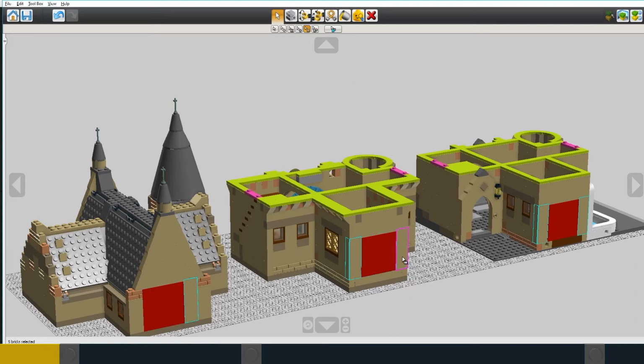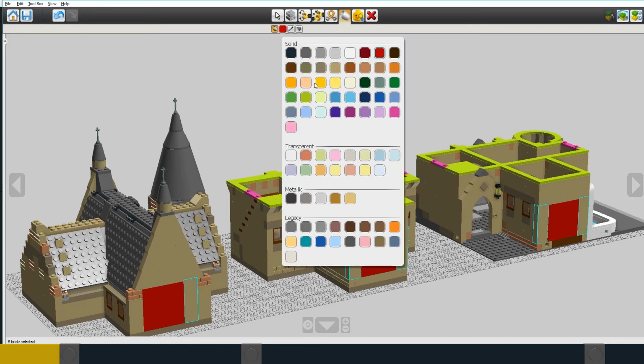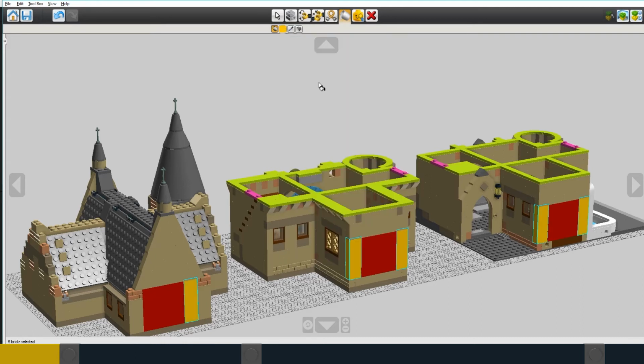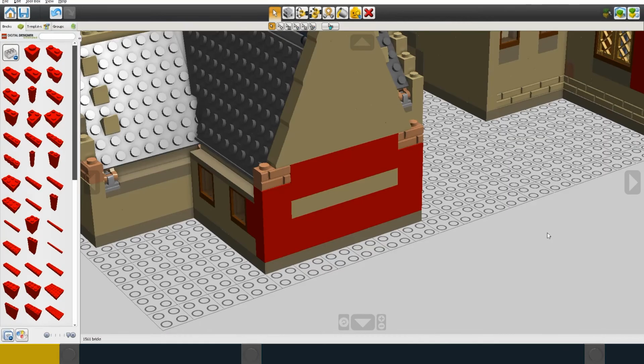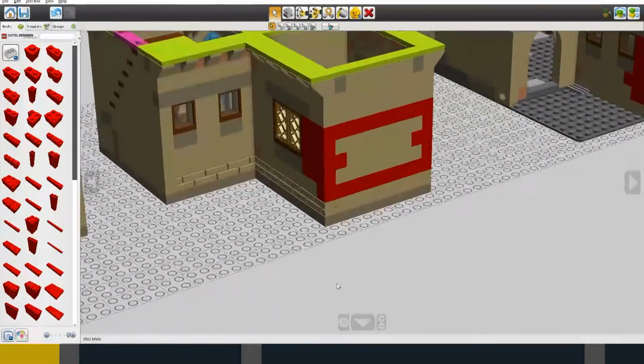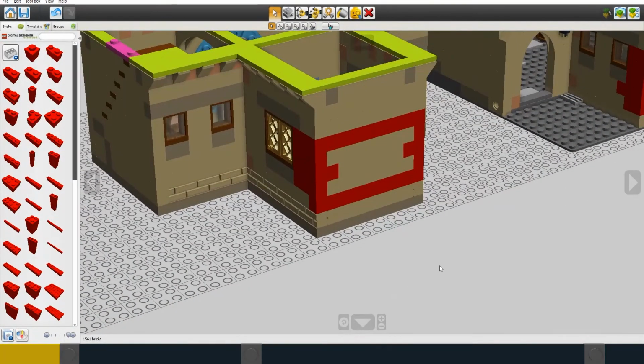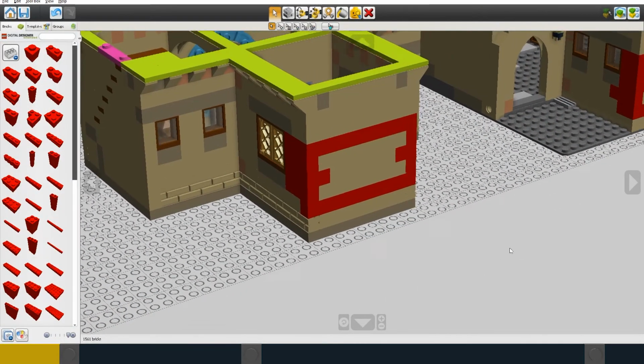But as I've gone round the exterior of the building, I've replaced many of these panels with other bricks so that I can provide details like door surrounds, window locations and other features. I'm not against using panels in the right places because they're relatively cheap, but they are also very plain and boring, they're not very strong and don't bind well, and I don't like using them for load-bearing walls.